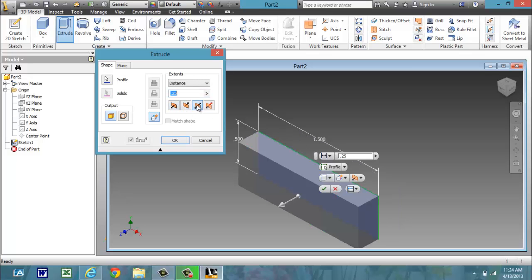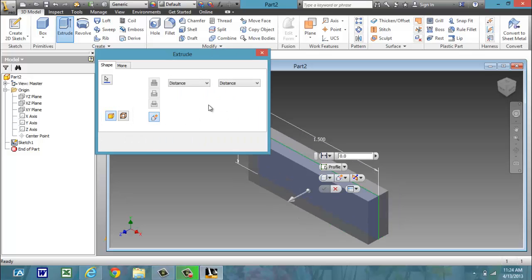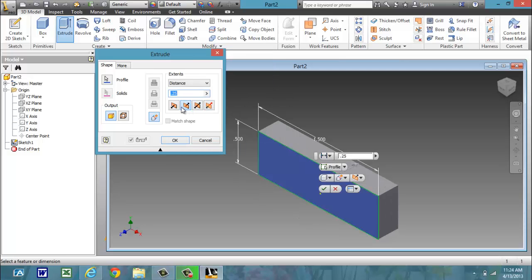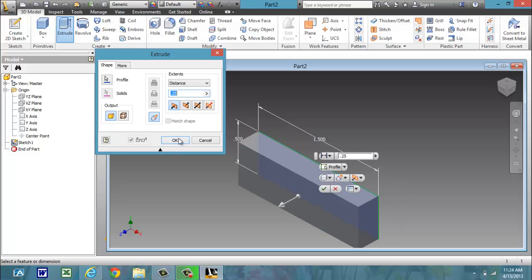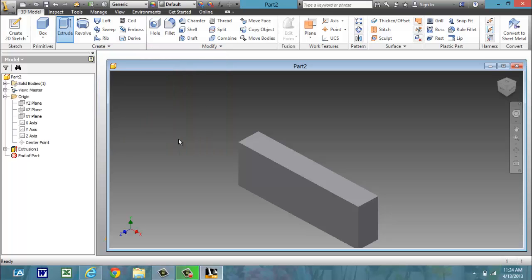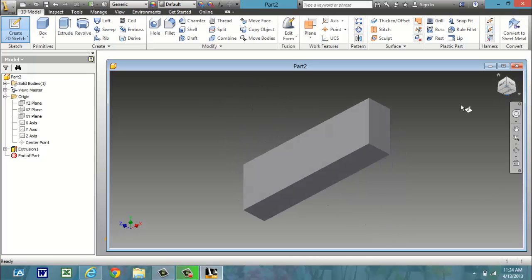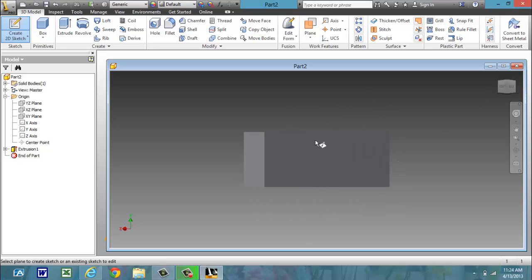You can click on the little house at the upper right hand corner of the cube. But here I'm showing you the different ways to extrude. You can extrude direction 1, direction 2, symmetric, which is equal on each side of the plane, or asymmetric, and you can choose the distance on each side. But for this drawing, I chose direction 1. So now I'm just showing you the different edges.